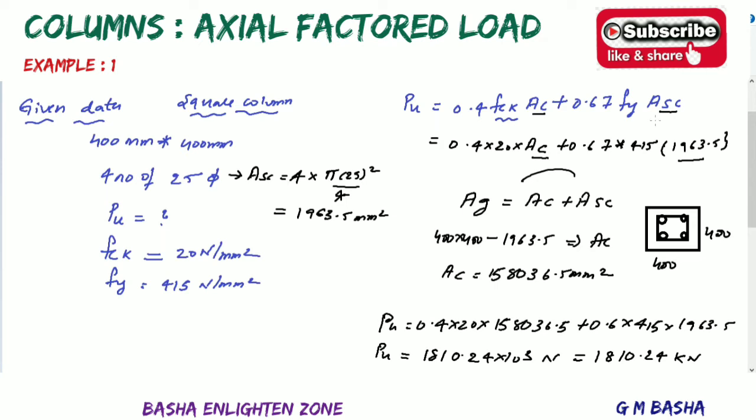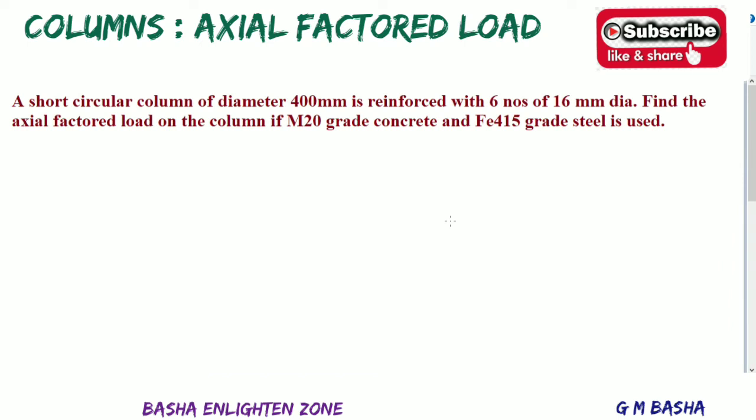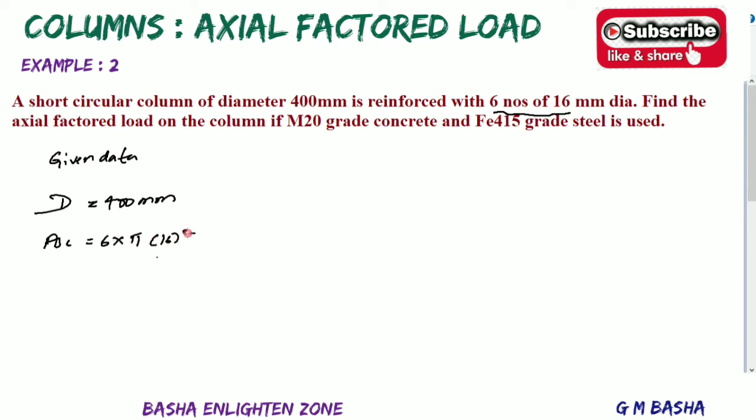In the same way, what is the difference between a square column and a rectangular column? The dimensions will be somewhat different, like 400 by 600, and you just take them as they are. But whenever a circular column is given, the rest of the data is the same. See here, according to the given data, a circular column of diameter 400 mm, with area of steel given as 6 numbers of 16 mm dia. So take down 6 into pi d square by 4. If you simplify this, you will get 1206.4 mm square.